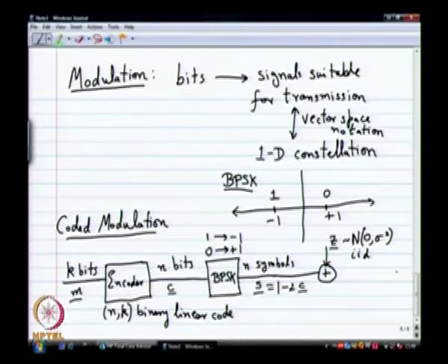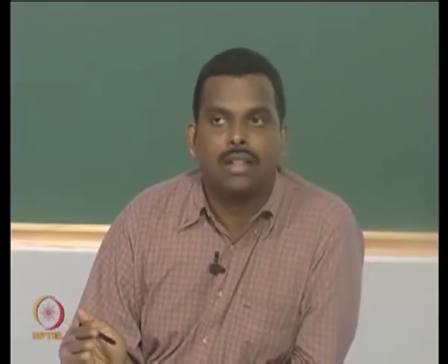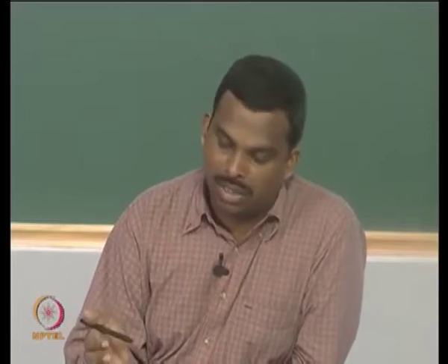So this is the assumption on the noise, and there is a very rigorous justification for it. You can start from a set of signals, let us say 2 signals, express them in terms of a basis like this, and then send that signal out and assume some n of t gets added to it. Then you design an optimal front end which is called the matched filter, and you look at a sufficient statistic, which will be just some noise vector being added to the representation of the signal in the vector space notation.